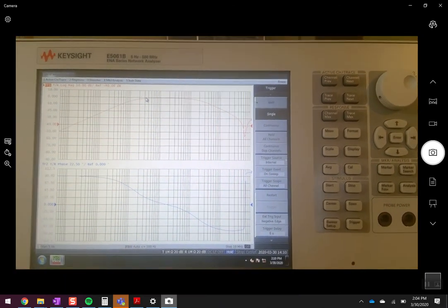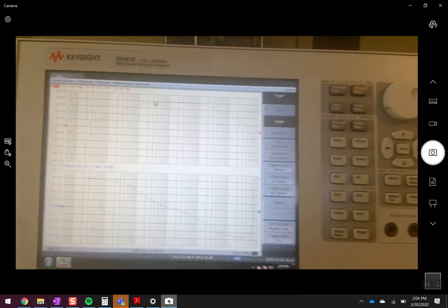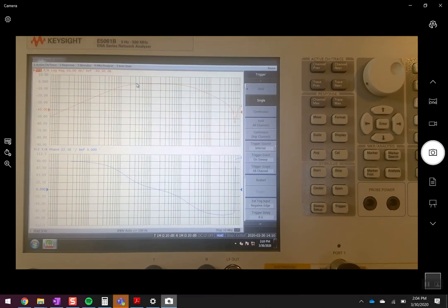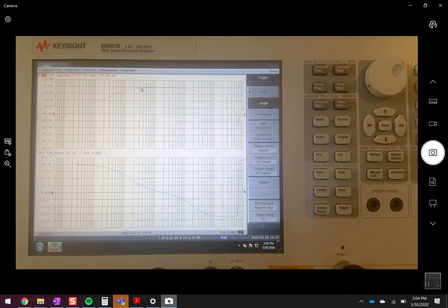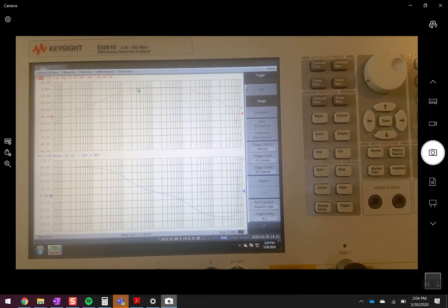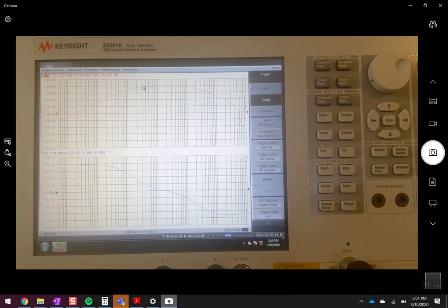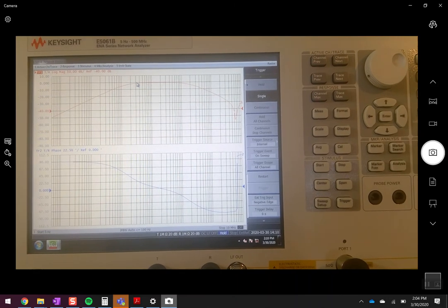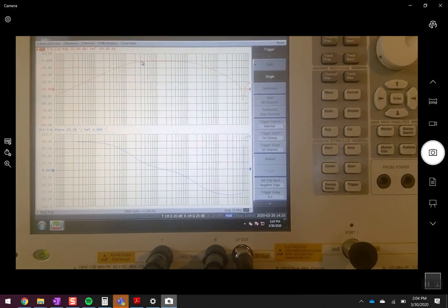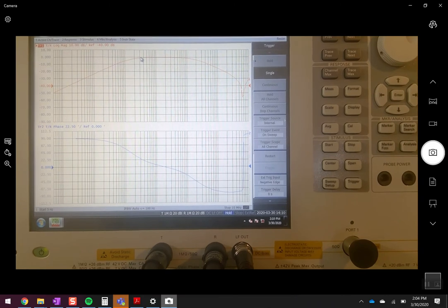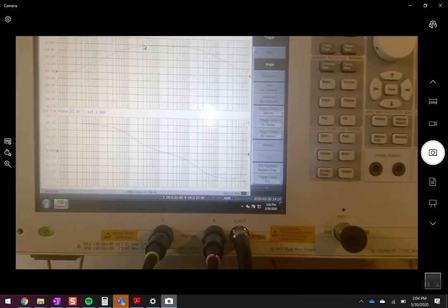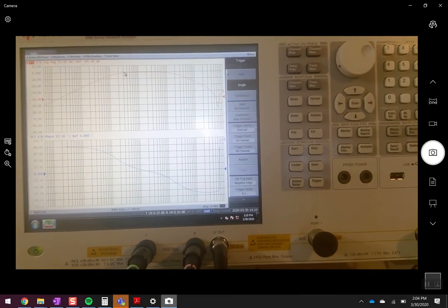And we get that very nice bandpass filter. Now we get this slightly odd behavior at high frequency, and that just has to do with some issues with the low pass filter. When you get to high frequencies, the particular design of our low pass filter has some issues that are beyond the scope of this course. So we don't really need to worry about that weird bounce up behavior at the end there in that high frequency range. But we can see we get this nice little pass band here.